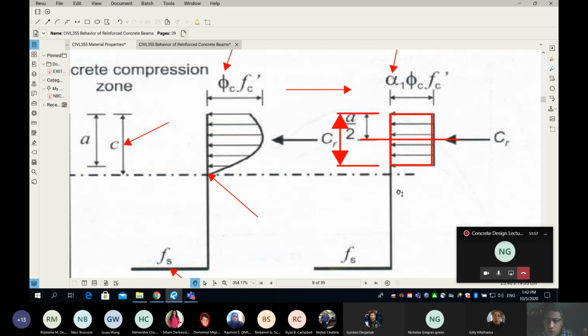Guys, hopefully you see, I know so far we still need to do more mathematical work, but at this point, all I'm asking you is to appreciate that when we transform the parabola into an equivalent rectangular shape, we get some mathematical advantage. We know right away that the centroid is in the middle of a, and the area is simply the length times the width. Are you following? I need to hear some noise.